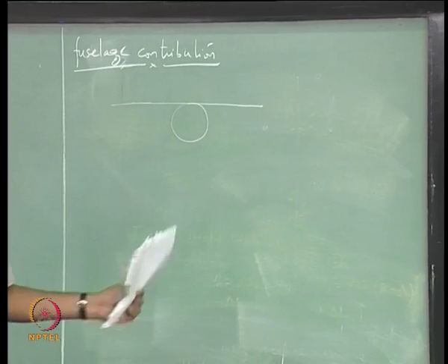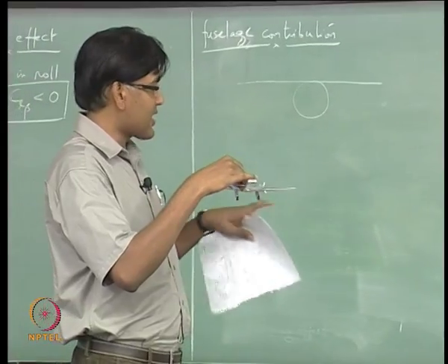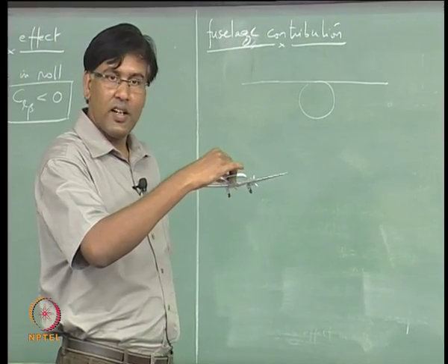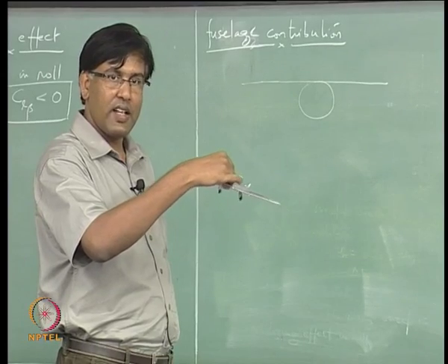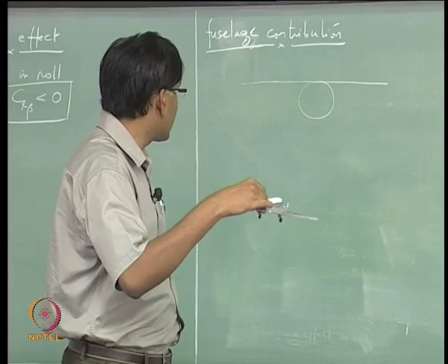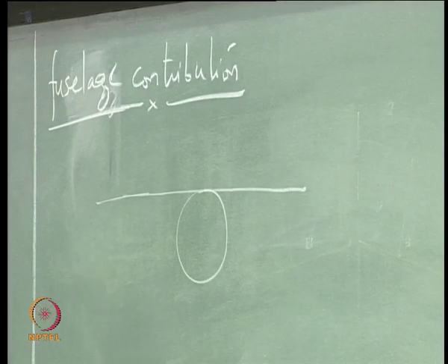So, I have a high wing here, and so for you it should be taken like this, okay. My x is into the board, right, and now I see a roll upset like this, and the airplane starts side slipping, right. This is how you should look at it. Let us see what happens when there is a roll upset.